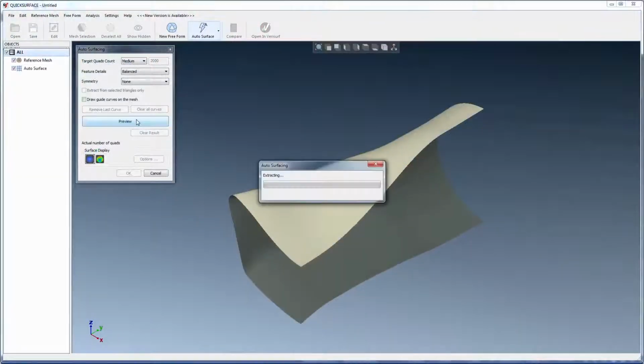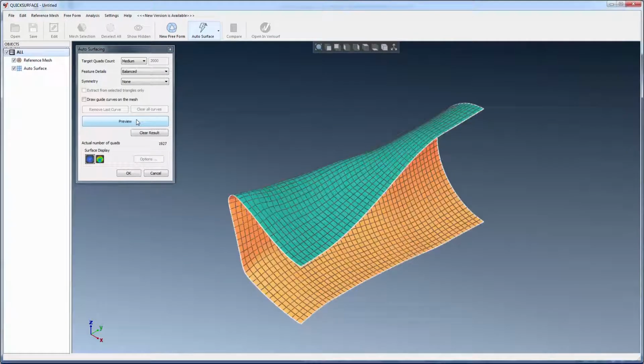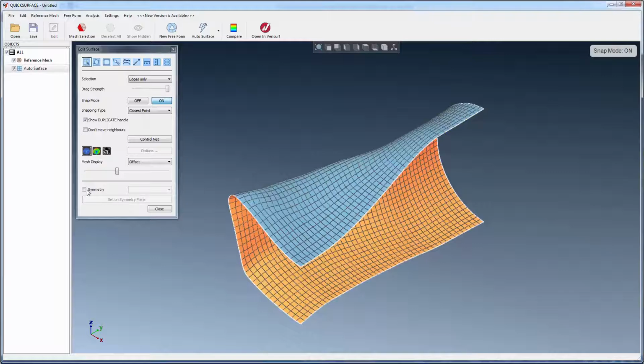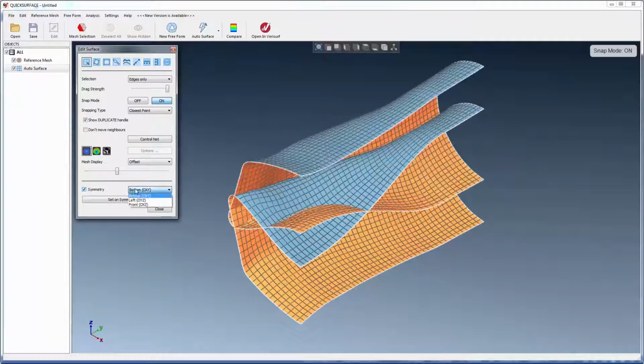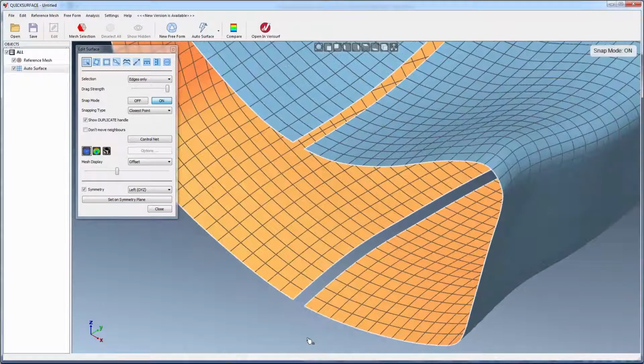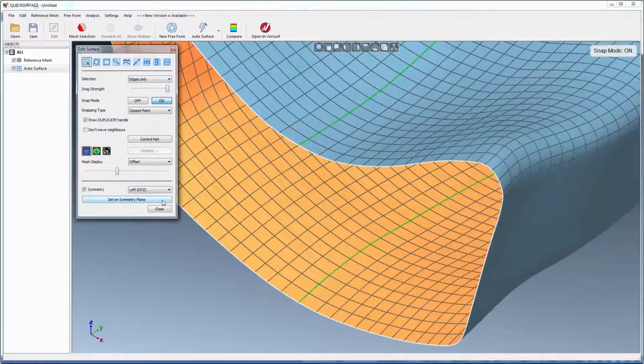Open meshes, those with triangles on only one side of the symmetry plane, can be modeled in a similar manner. After creating the first side, the surface is mirrored about the symmetry plane. Any gaps in the surface are resolved by first selecting the quad edges on both sides of the top and bottom gap. The edges are then joined by extending to the symmetry plane while maintaining curvature continuity.